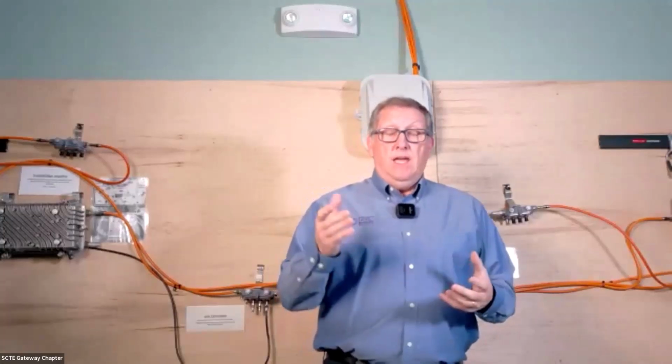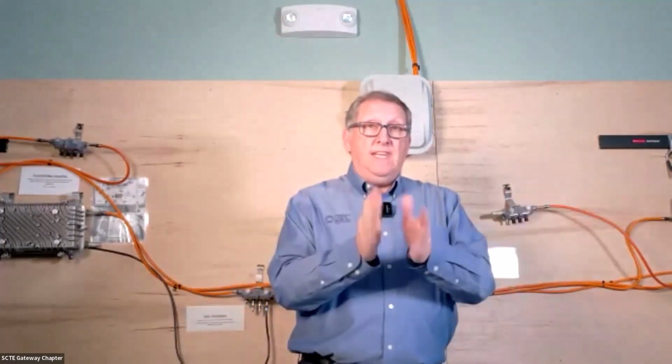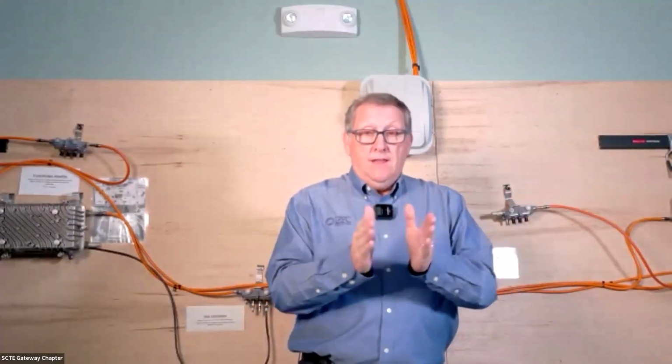But the newer world, the RFoG world, the EPON world, most of those actives, most of those SFPs, are looking at a -10 to like a -24 kind of window. -17 kind of falls into the middle of that. The actual range of some of these SFPs, once again, going by the different manufacturers, actually goes up to a -5.